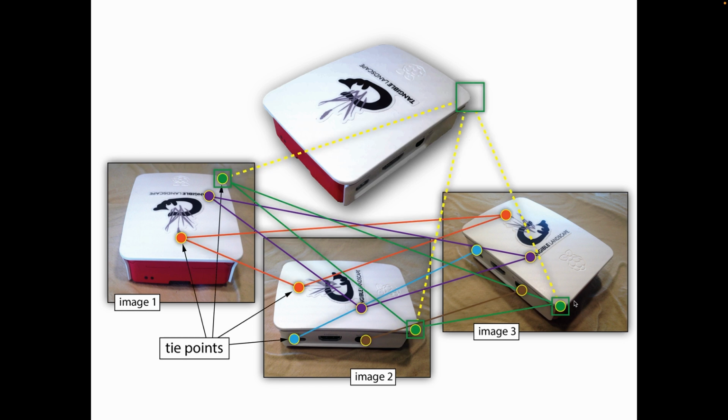And we're going to do this for a whole set of images, and then we'll be able to cross-reference those points and work out their locations and actually solve for what the overall 3D location is of each one of those points. And we're going to be able to use this for both our ground control points, which we'll be able to see in a subset of our photographs, as well as just generic points in the image.